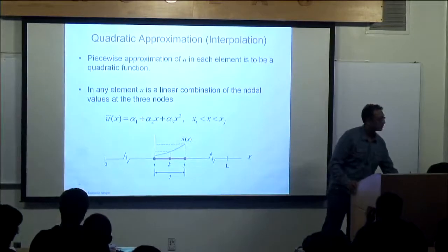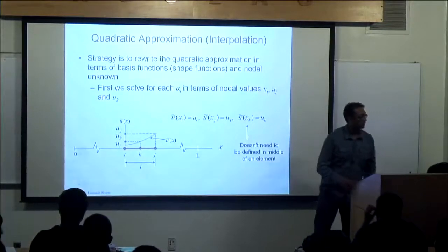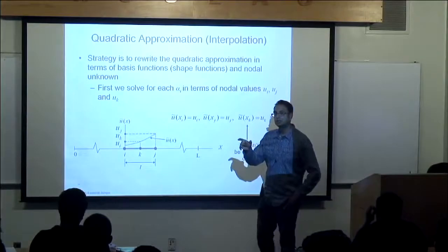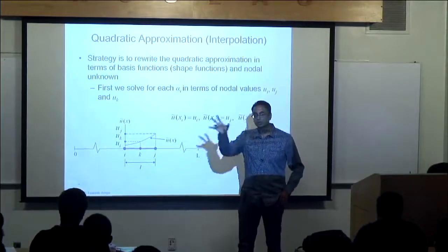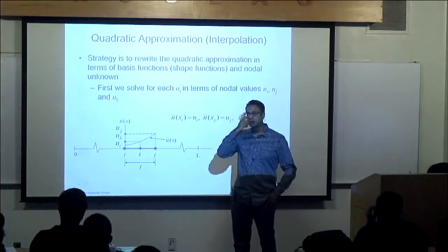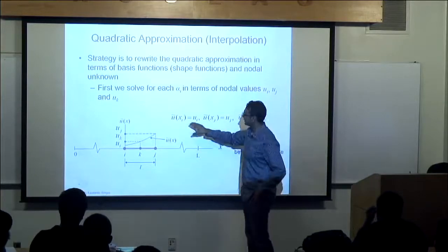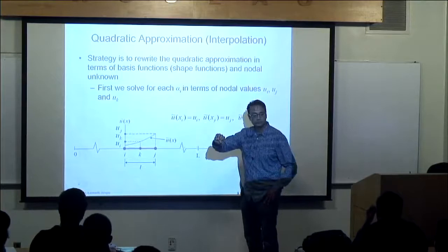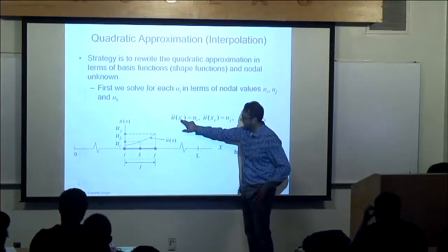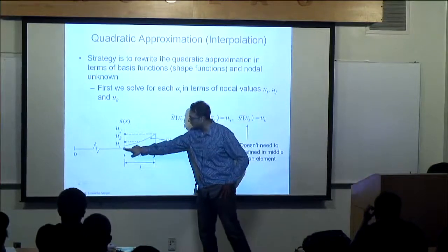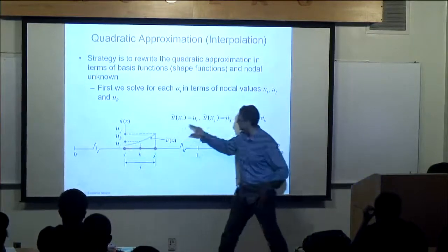Because these unknown coefficients have no physical meaning, and I need to connect them to other adjacent elements, I'll take the quadratic polynomial that I assumed and evaluate it at xi to get the value for the displacement there, which I'll call ui.